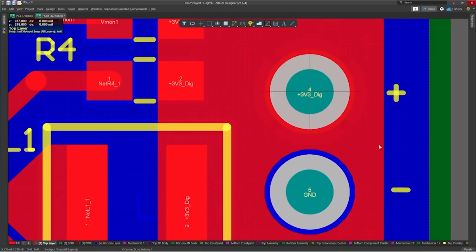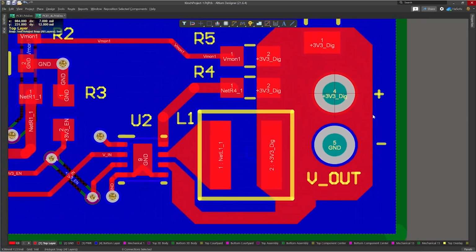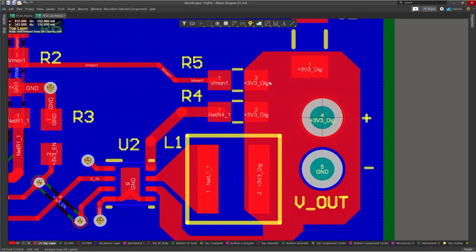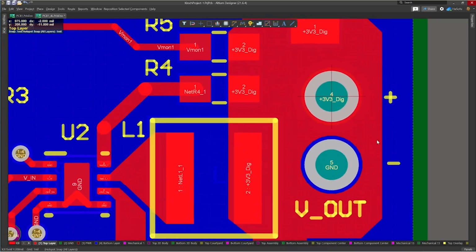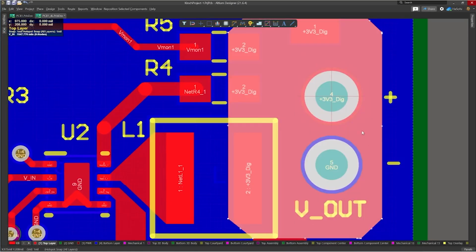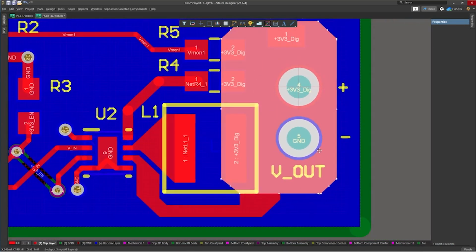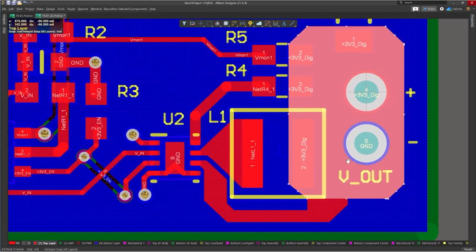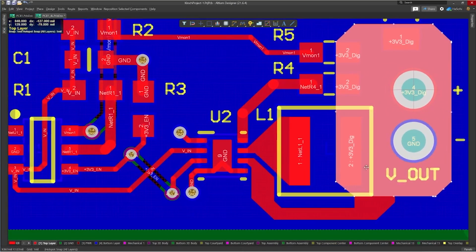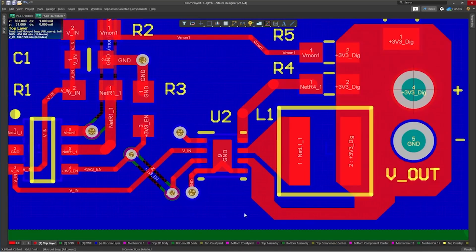Here we have copper polygon pour, and this lets me pour over multiple component devices without having to individually connect all of my traces. This is very useful because I can definitely supply enough current for the application, for my devices and what they need. This is another method as well. But oftentimes, if I know I'm going to a multi-layer printed circuit board, minimum 4-layer PCB, I like to use split power planes.